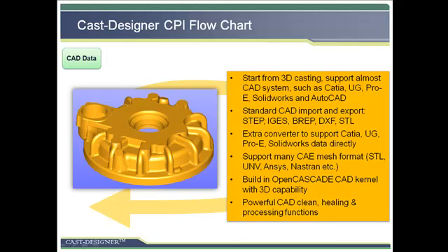Cast-Designer also supports many CAE mesh formats, such as STL, UNV, ANSYS, Nastran and more. Sometimes, if the CAD data comes from third parties and has quality problems, the built-in Open Cascade kernel, with full 3D CAD capability, has powerful functions to clean, heal and process CAD data.